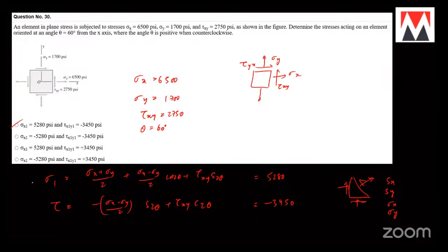Okay? So you'll get principal stresses sigma 1 in the form of sigma x plus sigma y. You can write this as plus or minus, or you'll write sigma max and sigma min is equal to sigma x plus sigma y by 2 plus or minus root over (sigma x minus sigma y by 2) whole square plus tau xy square. Like this you'll write now. Just previous to this one will be there. These are maximum and minimum. These are at any angle. That's all. So you put all the values which are given in this, you will get these values. Understood, Devasri?